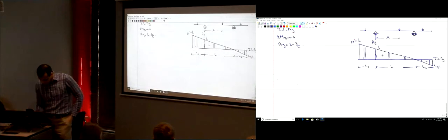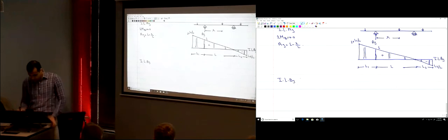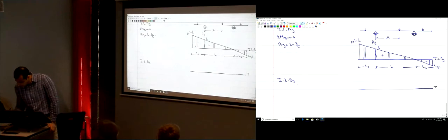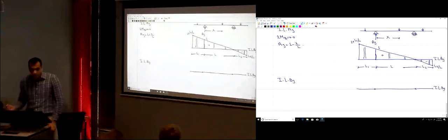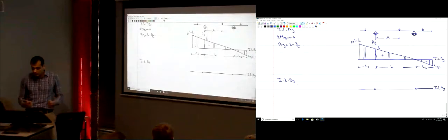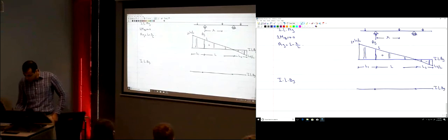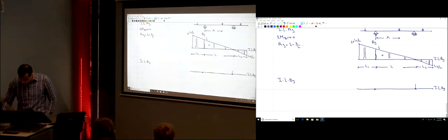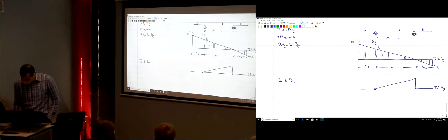So now the influence line of By. I'm not going to write the equation. Now we have a very simple rule. If you know the influence line of By over the single beam, just extend it over the overhanging parts. So here, the single beam, those two crosses represent the supports. For By, it looked like this: 0 here and 1 here.